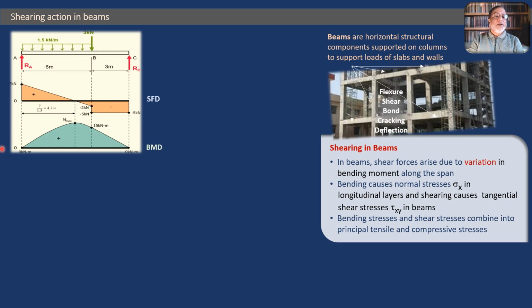In structural mechanics, we have drawn these SFDs and BMDs for very complex beams also. Now, if we look at the bending moment diagram, we find that the bending moment is changing from one point to the other throughout the beam. Nowhere do we find a constant part in the bending moment. It may be increasing or decreasing, positive or negative.